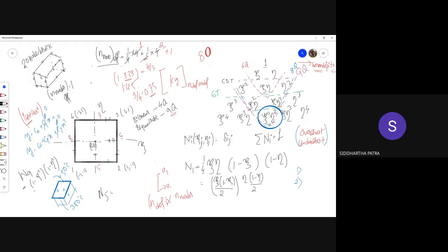Now these mid-side nodes are only shared with 4 elements. One that sits on top of it, one that sits in front, and one that sits on top of the element in front. So this node would be shared with the element that sits on top of this element on this surface, one that sits in front of the element on this surface, and one that sits on top of the element that sits in front. So it would be shared with 4 elements, so 12 by 4.